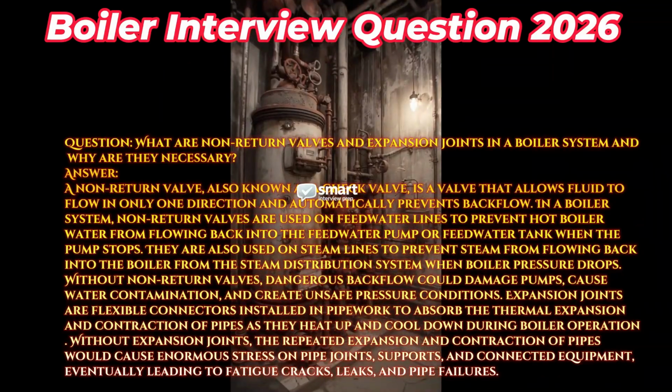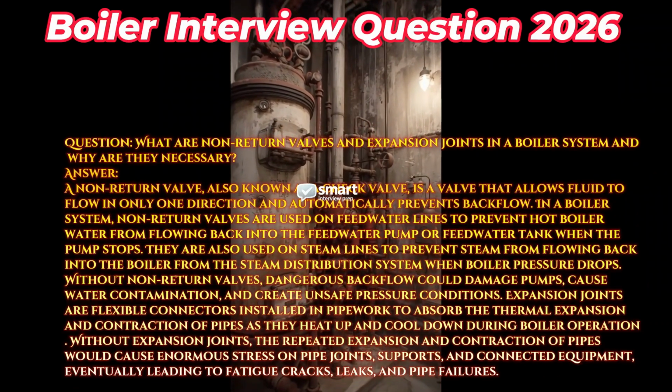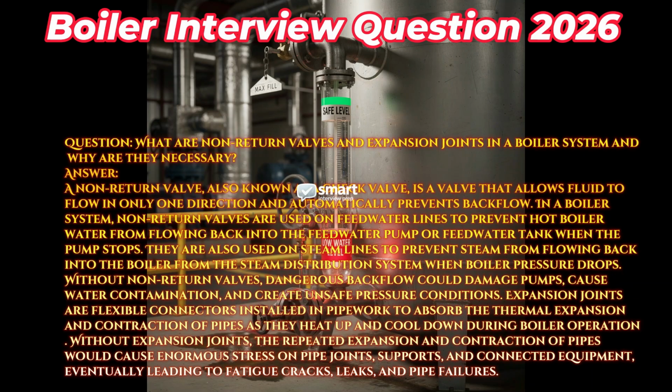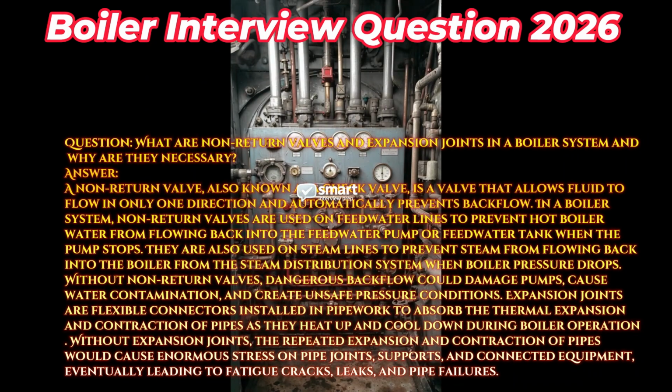as they heat up and cool down during boiler operation. Without expansion joints, the repeated expansion and contraction of pipes would cause enormous stress on pipe joints, supports, and connected equipment, eventually leading to fatigue cracks, leaks, and pipe failures.